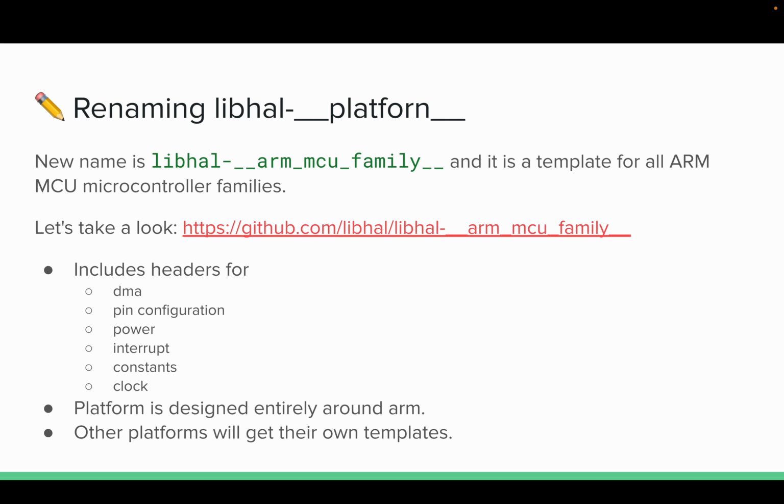And then when you look at STM stuff, it gets so complicated that even if I wasn't trying to build something generic like this, it's hard to keep track of just looking at it when you're using it yourself. So it's honestly just an absolute pain in the butt to do clock tree stuff for STM devices that I've seen. There's a maximize all clocks API, which tries its best to maximize as many clocks as possible. There are some clocks that won't be able to be maxed out completely.